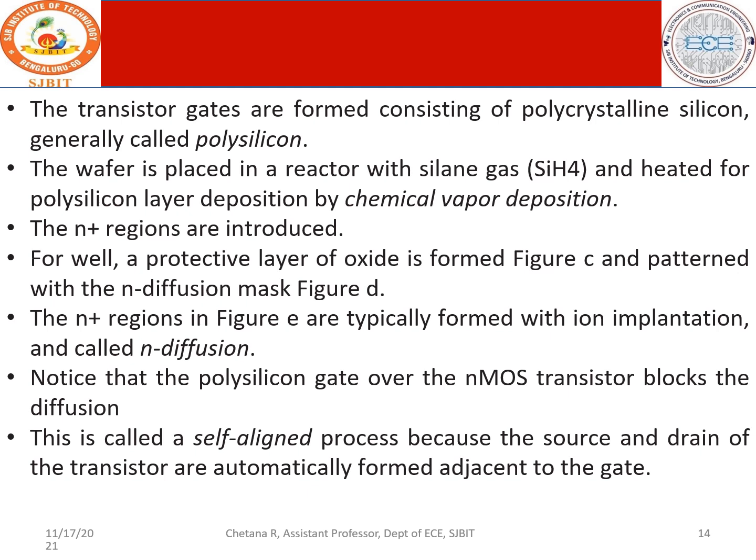Take a gas, silane gas, it is SiH4. Heat it to a very high temperature. When you heat it to a very high temperature, the gas is converted, almost creating vapors. That vapor is made to deposit, and that is how your polysilicon layer is created. So the polysilicon layer is needed on both the well structure as well as on the substrate, so parallelly polysilicon is created. So what is the other name for your polysilicon? It is nothing but your gate.